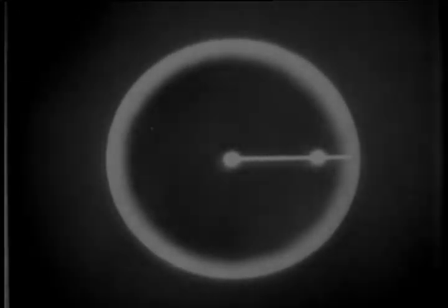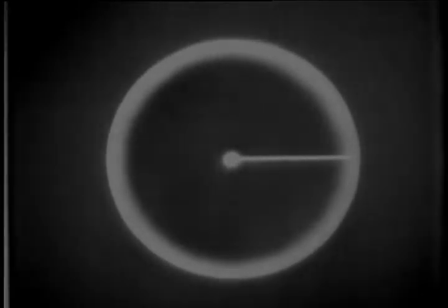Okay, you know how the target signal is formed and how to measure range on this PPI. But how about azimuth? Well, those coils that cause the electron beam to sweep back and forth to form the baseline are designed to rotate freely around the neck of the tube. Since it was the current flowing through the coils that produced the baseline, when the coils rotate, the baseline sweeps around the scope.